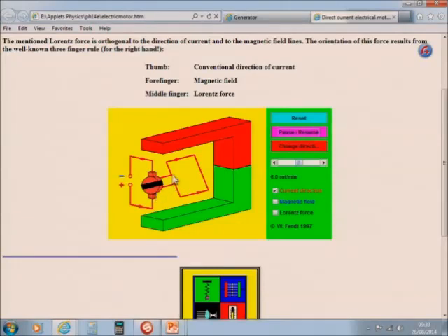All right, now why do we want that current direction change every 180 degrees? The reason for that is so that this armature keeps on experiencing a force in the same direction, which then will give us continuous motion. My electrical motor will keep on turning in the same direction. If I didn't have split rings with a direct current source here, then this armature would not have a continuous turning motion.